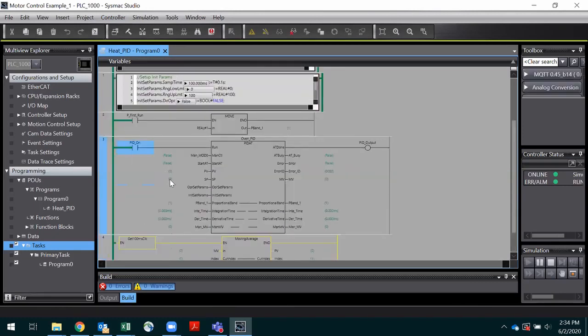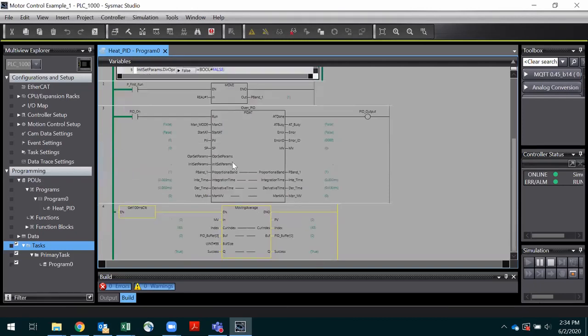Okay, so give it a set point. You won't be able to write anything to the PV now because it's being overwritten by that floating average. So you can write a set point of say 50, give it 1 second on the 2 time tuning variables. Then start the block up. Perfect. Now do an auto tune. There we go. It's still a bit jumpy.